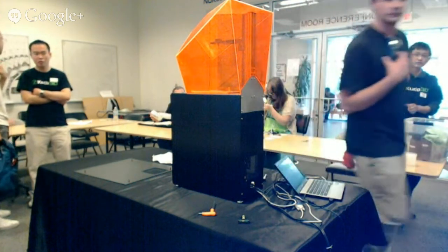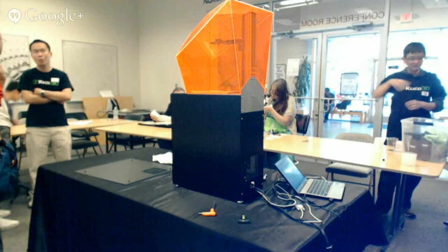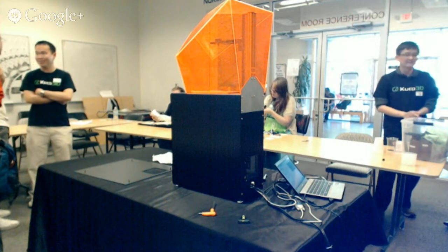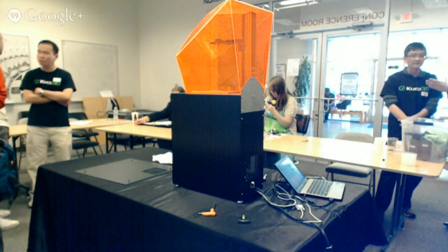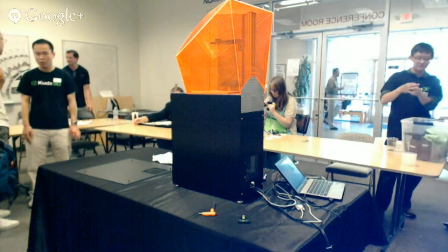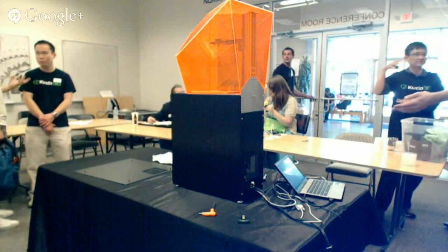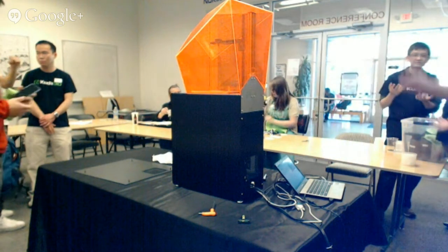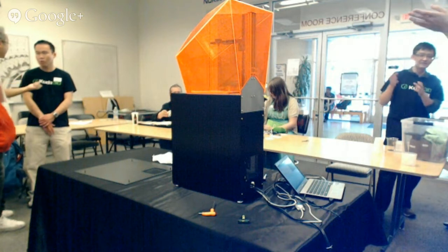Unlikely, and it's both good and bad. It would be great if one dead pixel would make a big difference, because that means my prints would be really, really precise. The reality is that the pixels are not tiny lasers, right? This is just light, and the light is kind of fuzzy and edgy. So one dead pixel probably won't even result in a hole. You'll see it as a surface defect, kind of like these streaks here, but you probably will not even get a hole. The light bleed from the other pixels around it will probably fill that in. It'll probably be solid.